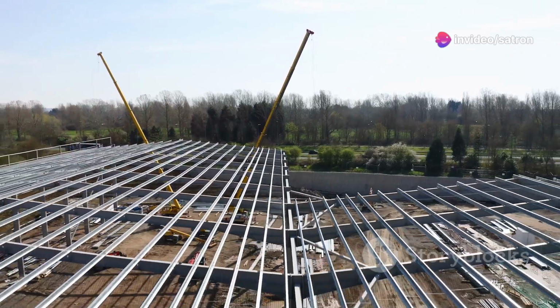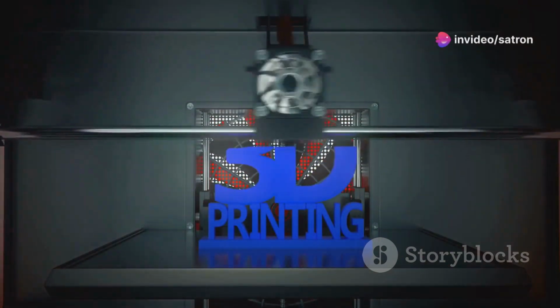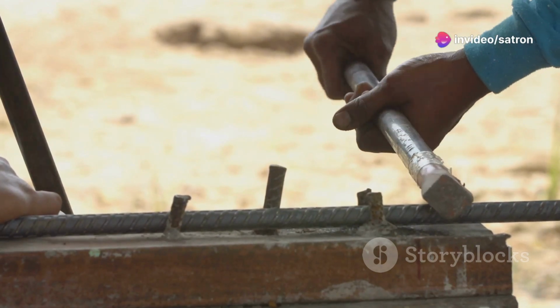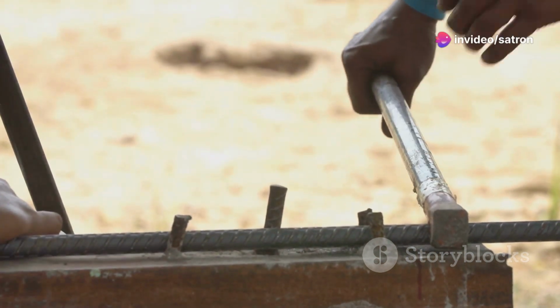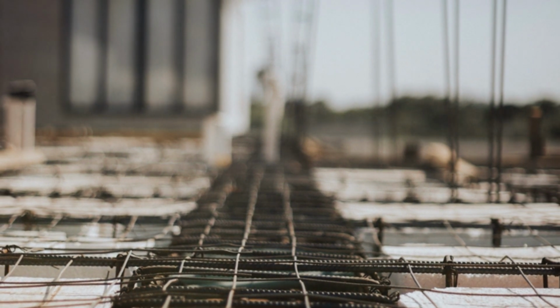Another important use for plates is as stiffeners. Think about a thin-walled beam. Under heavy loads, the web, the vertical part of the I, can buckle or distort. Stiffeners are plates that are welded or bolted to the web to prevent this from happening. They add rigidity and help the beam to carry the load more effectively.